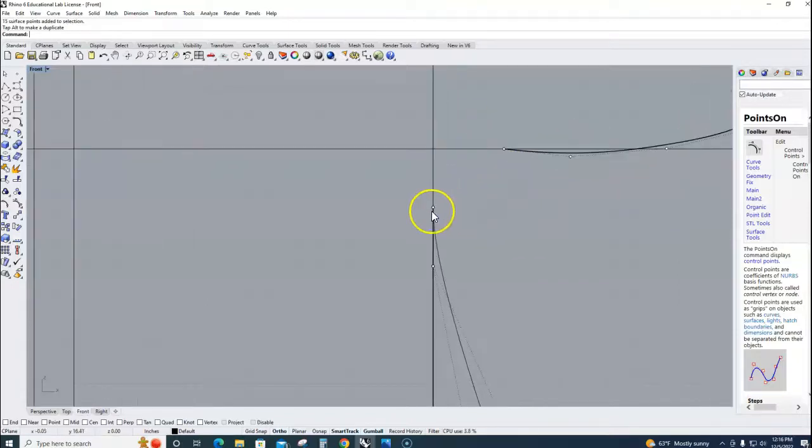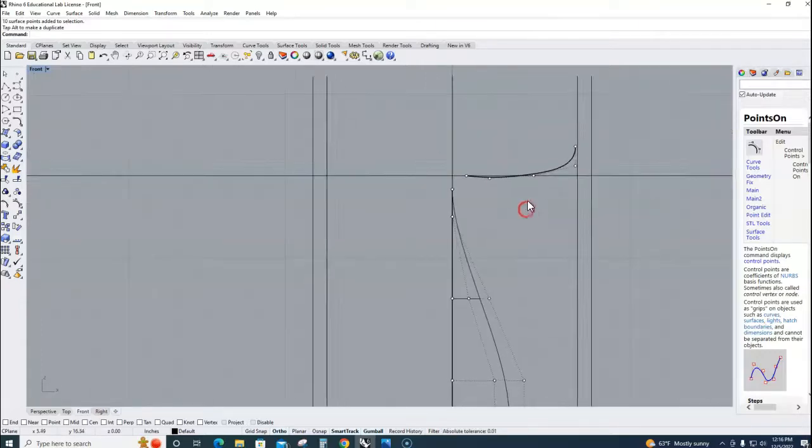I'm also looking to make sure that Rhino has enough room to give me a really nice clean transition, right? So maybe I'll just take it up to here, like I'm looking at this grid right here, and I'll pull these guys back up to there so that it gives me a nice little tight curve.